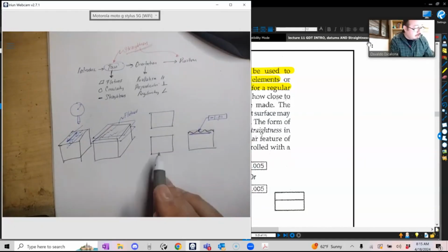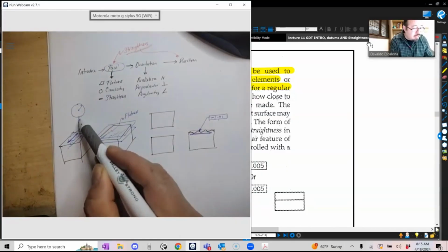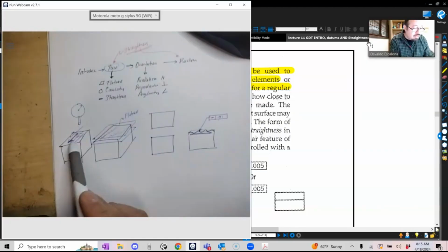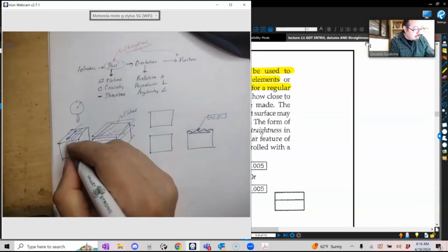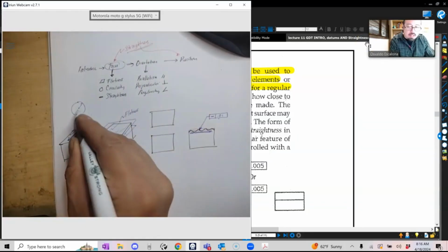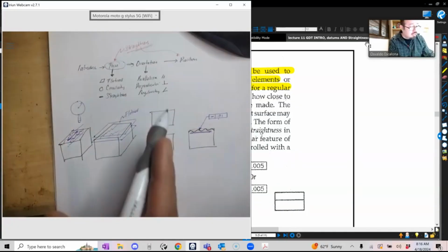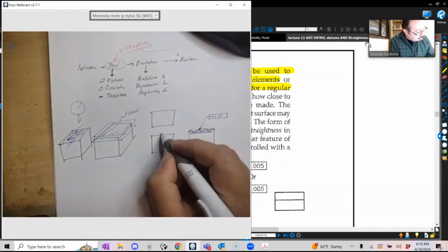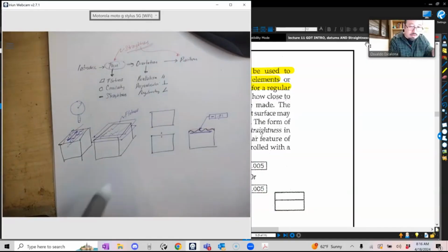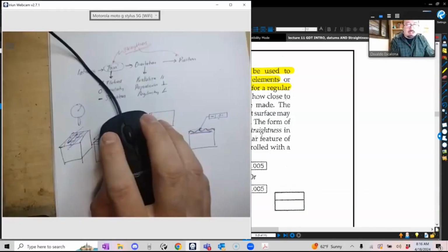Okay, so if you were to make the measurement, if I grab my dial indicator and move along this line, which I just made here, and I want to check the straightness of the next path, I will have to lift up my dial indicator and take the next measurement. Right, each of the measurements is independent of each other. Okay, so if I were to look at it in the front view, this is my tolerance zone, like two points, right? Because they run across. So my dial indicator will go in and out of the page in this view, independent of each other. Okay? That is what straightness is.